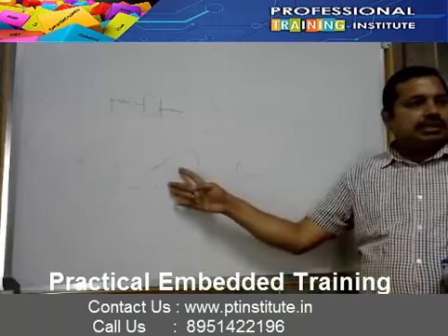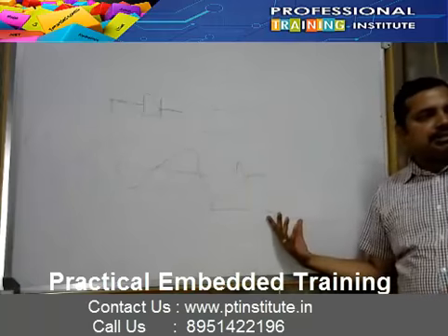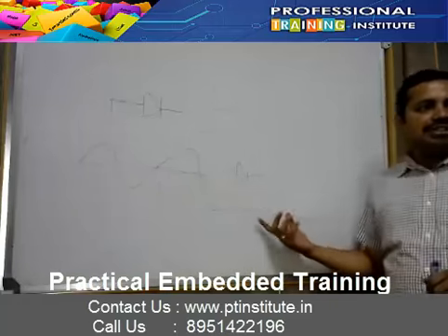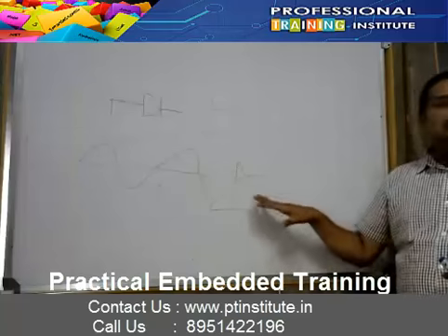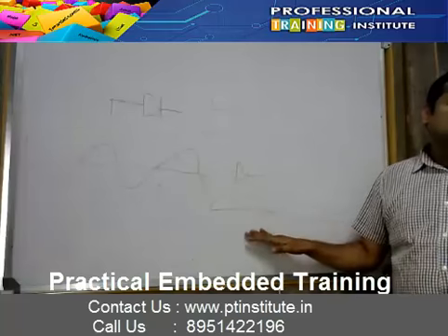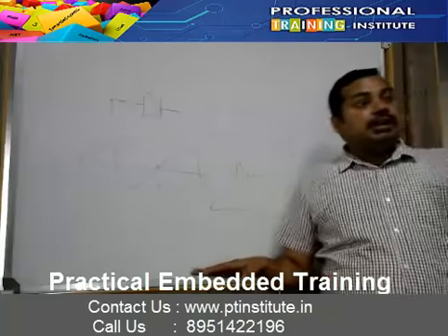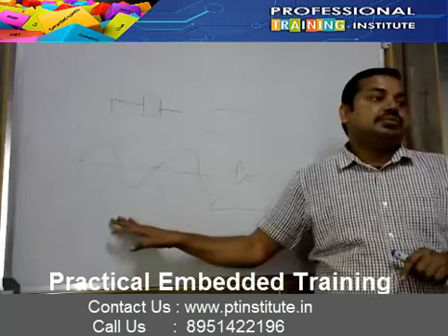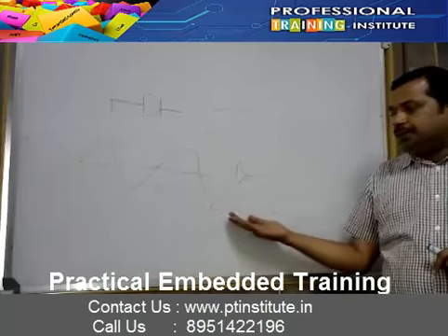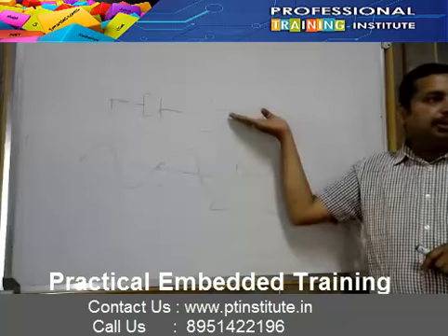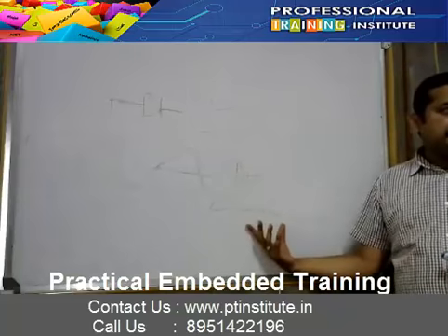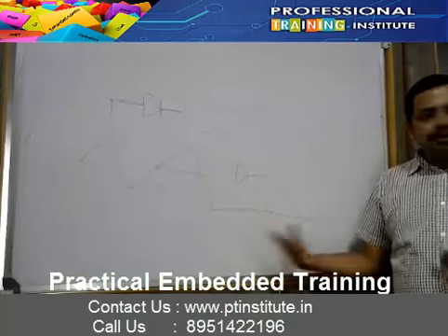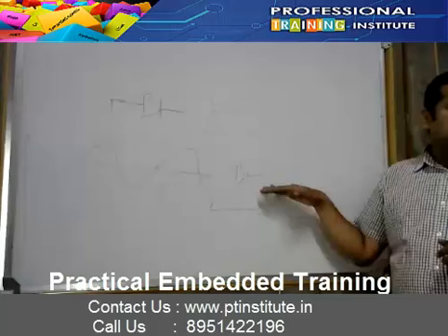I am asking, this is AC, right? Is this DC or AC? AC. And this is also AC. No, this is not AC. This is not alternating. AC must be alternating, which means it should go negative in the other direction also. So it's not a pure DC either. It's a pulsating pulse, a half wave rectified pulse. You have to make it DC. It's not yet DC.